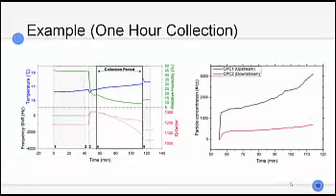So moving on to the results, I figured I'd start by just showing kind of how we get our numbers out of this. So on the left here is all the information we get from the box, so to speak. So on the top is temperature RH. I'm not going to go into it too much, but I'll just point out that we didn't do any temperature correction yet, just because the effect of that temperature is much lower in magnitude than the effect of the mass we're adding. And then the bottom, you can see the frequency shift in black during this collection period, and then you can also see a slight drop in quality factor. So the idea is that we want to compare this information to those CPC concentrations.